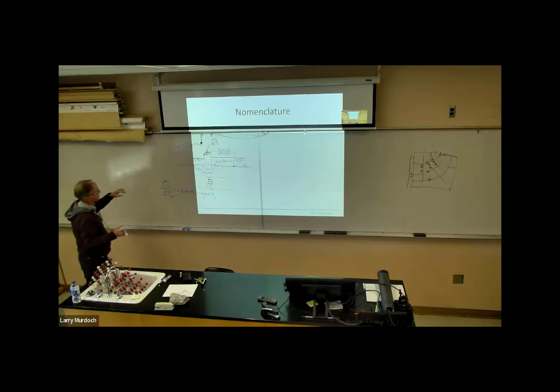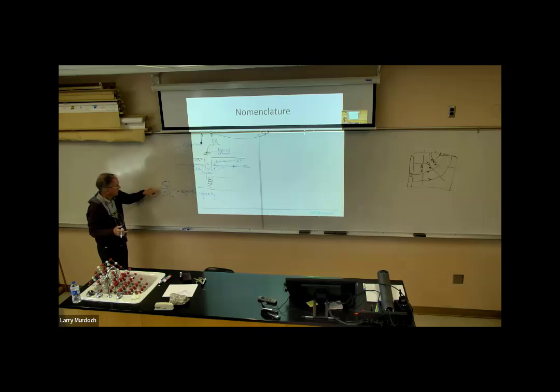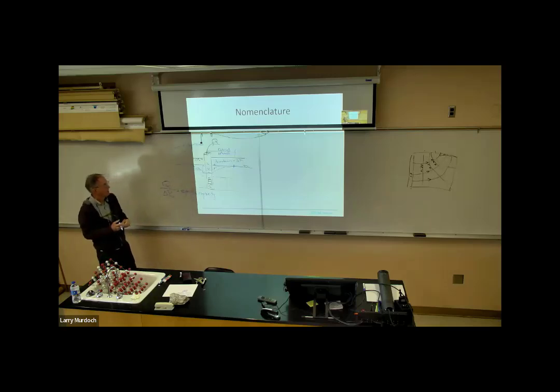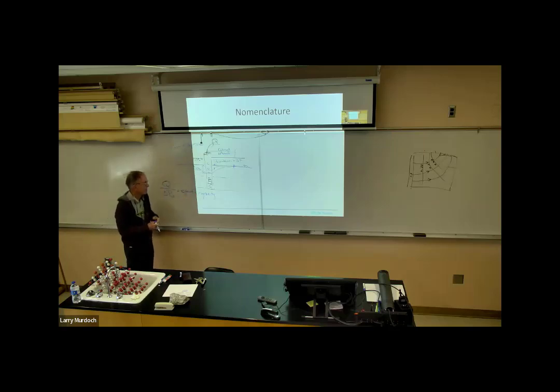So increasing this causes that to increase, and ultimately we're going to hit a limit that will damage the pump. And so there'll be a limit to the drawdown that we can have. That'll limit the flow rate through this specific capacity.